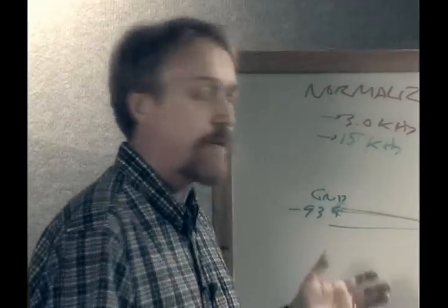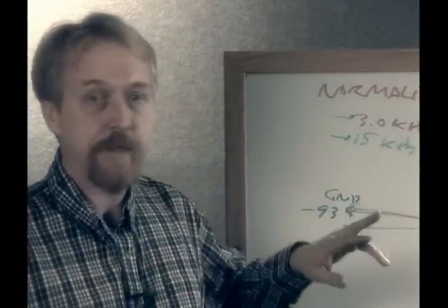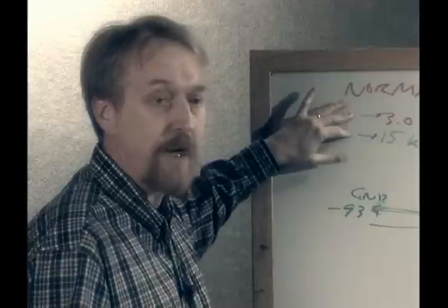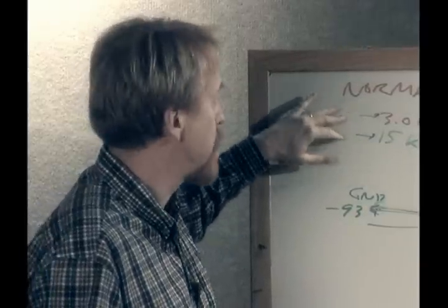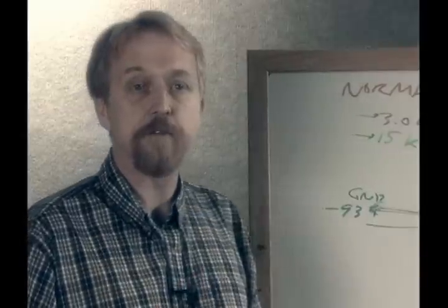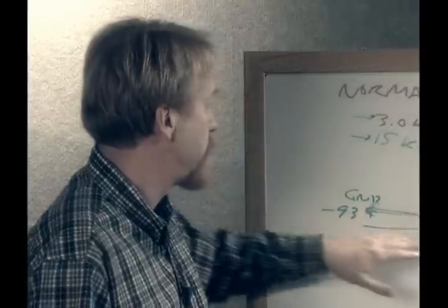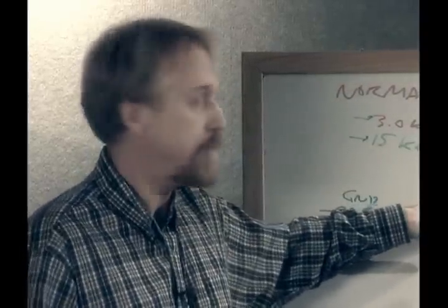Okay, so just to kind of wrap this up and summarize, what we've done here is to build a metal detector that can be operated at either of 2 frequencies in order to allow the operator to pick the one that's best for his application. Or we allow the microprocessor to look at both sets of data simultaneously and pick the most appropriate, as well as having the ability to remain balanced to dry sand and salt water all the way up and down the beach. And I think the combination of these things is going to make this an extremely powerful detector in the field.